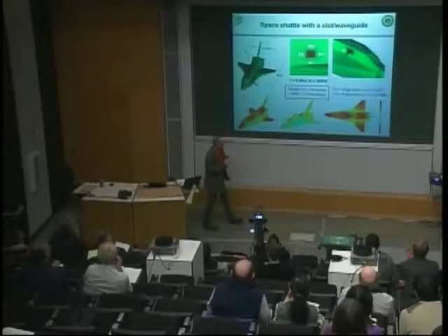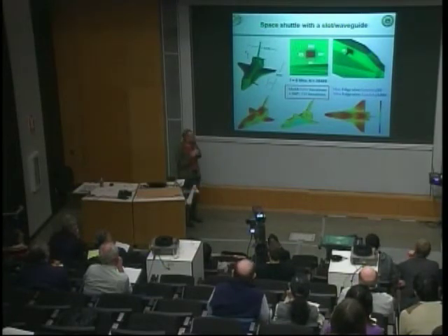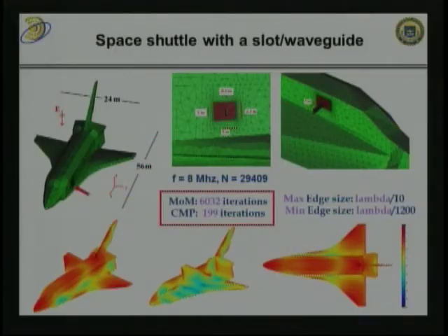Previously, in the olden days, engineers would be very reluctant to properly mesh an object like that, because they knew that the solver would not converge. Now, this day and age, we don't care about it anymore. We just sprinkle in more and more points, more and more triangles, in order to better approximate the true geometry of the object. We're no longer afraid of our solvers stalling. They will converge. You see here that the number of iterations of this thing without preconditioner is 6,000. It's huge. With preconditioner, it's still 200, but it's much better.